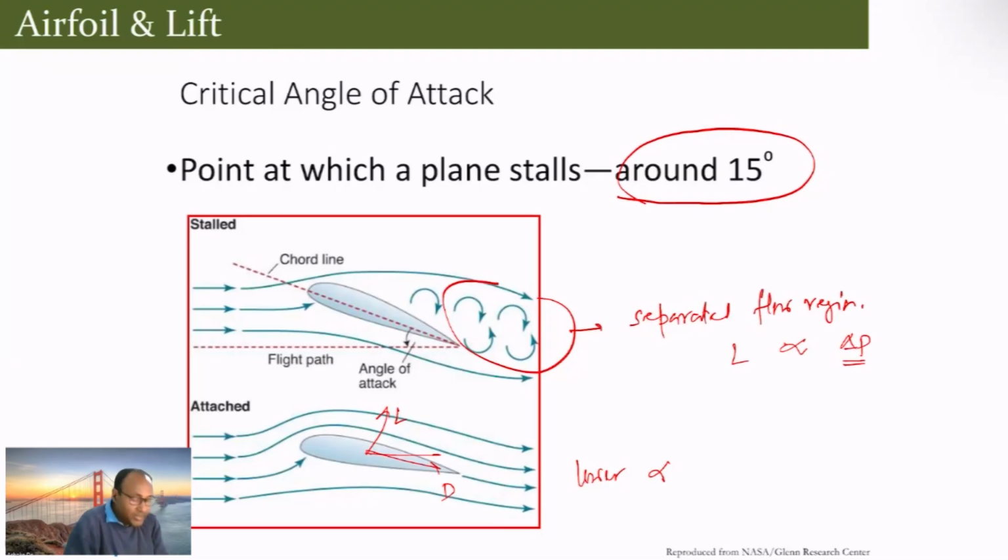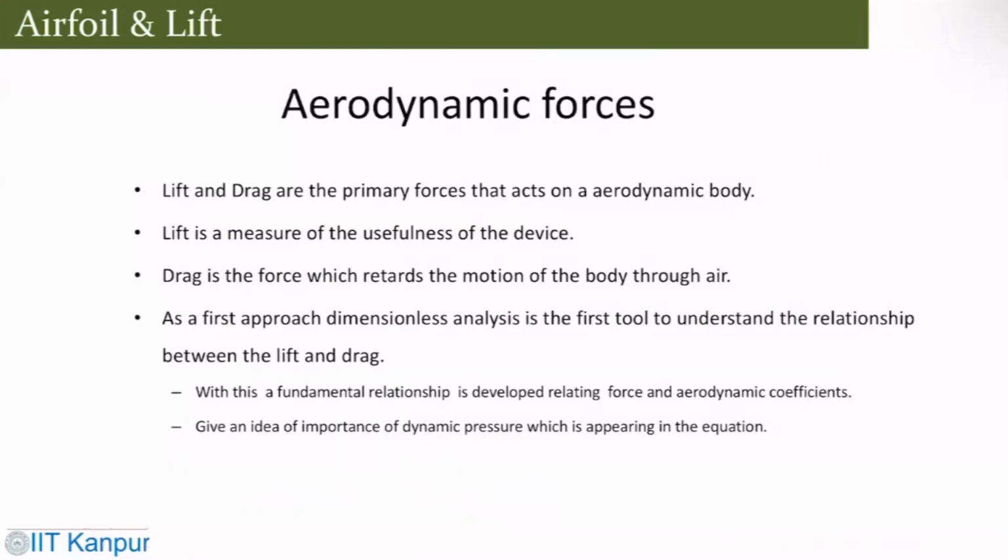But here this is going to be a problem. When separation occurs, you have an adverse pressure gradient, not a favorable pressure gradient. So lift actually starts decreasing. Lift and drag are the primary forces that act on the aerodynamic body.